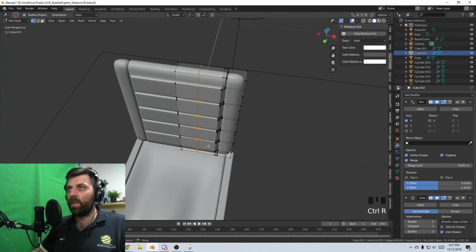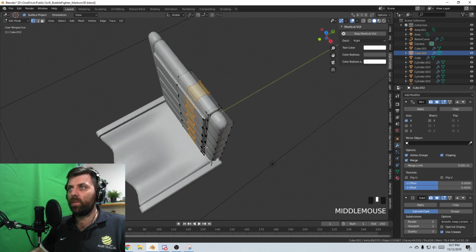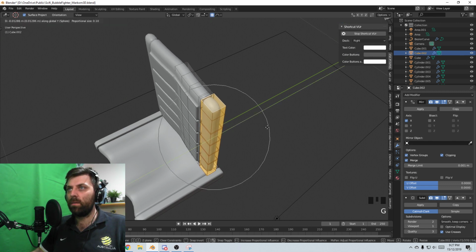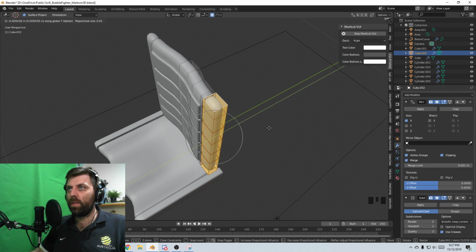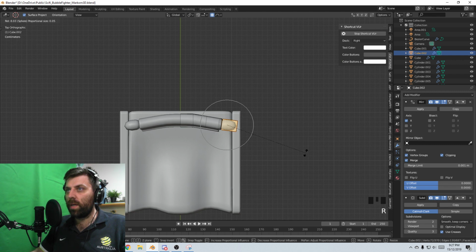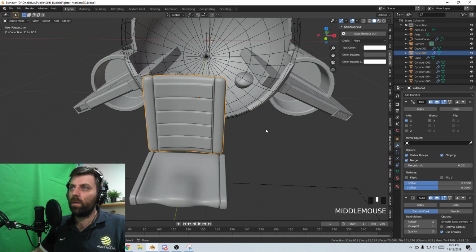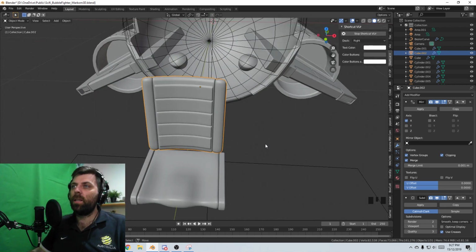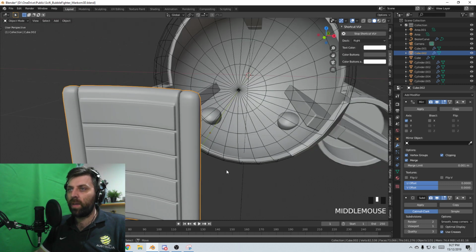What I will do is probably actually put another 2 edge loops in here. I'm going to grab this whole section, Control L. Let's turn on that proportional editing, GY. Bring that in like so. And let's rotate that around. There we go. And so now technically when we put that angle down a little bit, we should have a little bit of extra oomph in there.